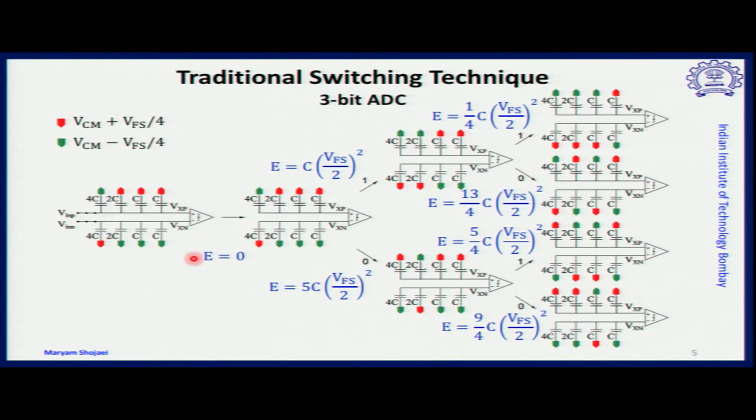What about the other plates? What are we going to store on the capacitors? The same way we proceed with the single-ended version, here also we assume at either site, V in P or V in N, a well-defined DAC level.